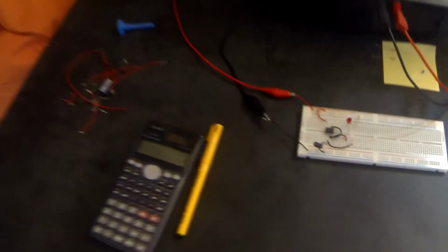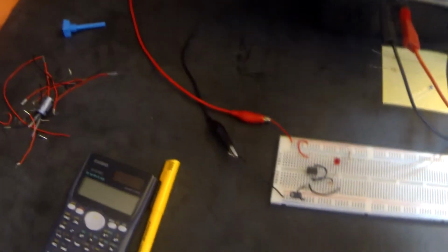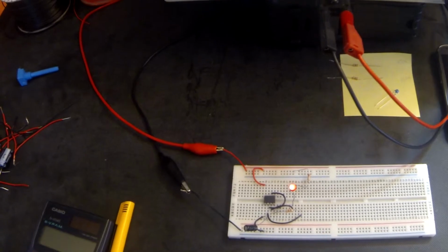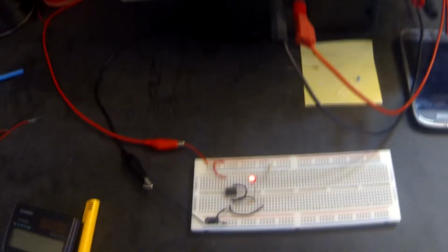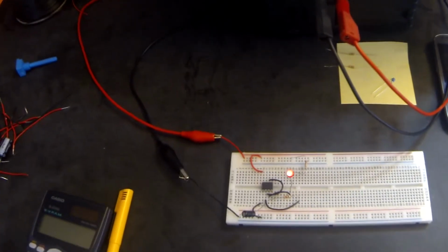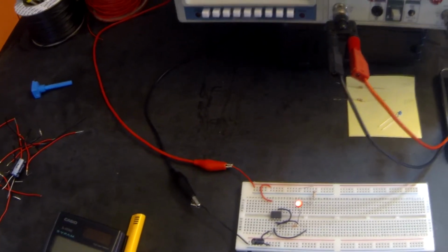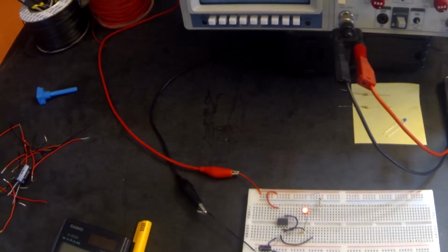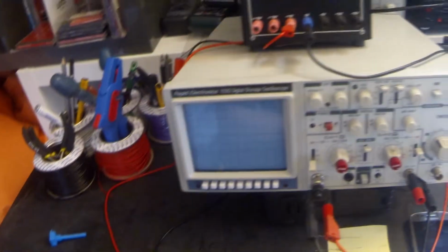So I built my circuit using the values 2.2 k ohms and a 1 microfarad capacitor. I'm going to turn the circuit on and the LED should flash. Now, that LED is actually flashing at the moment. The problem is it is flashing too quickly for you to see. It's flashing many times a second. We certainly wouldn't be able to measure that with a stopwatch as in the previous tutorial. So we need to now use this piece of equipment here called an oscilloscope.